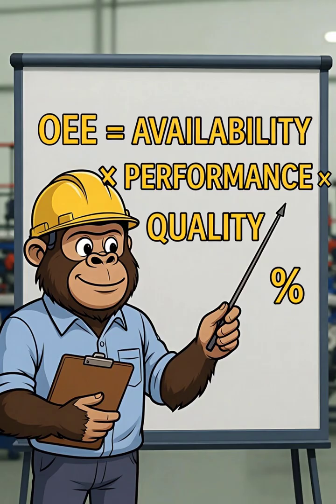Even though each individual number looks great, 90%, 95%, 98%, when you multiply them together, you end up with 84%. That's the brutal math of OEE. Every loss compounds. A small problem in availability combined with a small problem in performance, combined with a small problem in quality, and suddenly you're losing 16% of your potential output. That's why OEE is so powerful. It forces you to see the true picture.